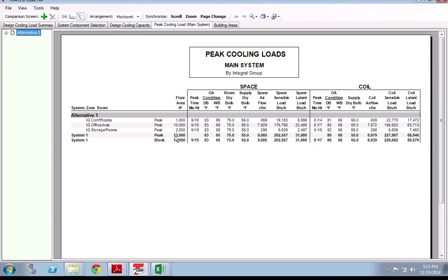It will then show the peak, and this number, this 88 or 227, this is actually the sum of the peaks, which is a terrible number in the sense of if you were to add up all the rooms when they were in their worst situations, what would that number be? And then you can actually see if you were to find when the whole building peaked together, what is that number? So that number is often less. Here they're very close because we don't have that many rooms.